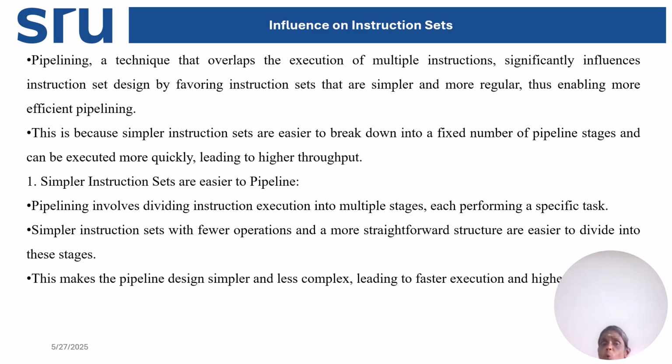So it involves overlapping of execution of multiple instructions. How we overlap significantly influences the instruction set design, by favoring instruction sets that are simpler and more regular, thus enabling more efficient pipelining. And one more restriction is there: we cannot apply this pipelining concept to all instructions. Only simpler instructions can we apply this pipelining concept to.